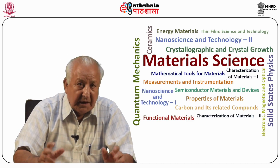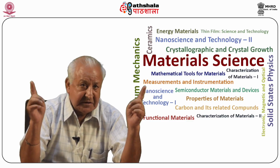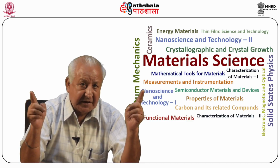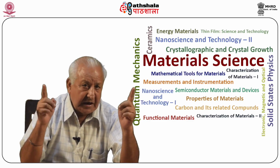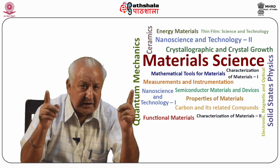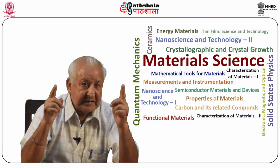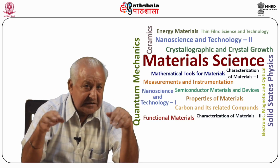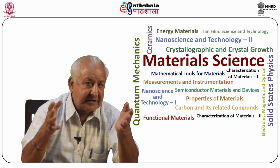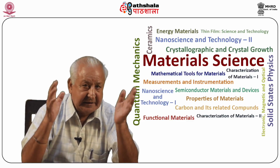Generally, it is a practice to restrict the area of the specimen to be investigated and contributing to the diffraction, which is achieved by inserting a selected area aperture, giving selected area electron diffraction, abbreviated as SAED or simply as SAD.